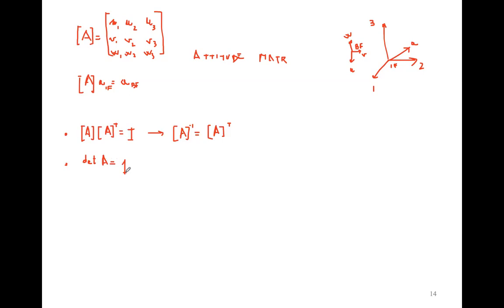I'm not going to reintroduce it, but there is another representation. This is the direction cosine, but you can also represent the same matrix with 3 different rotations. The 3 different rotations are given through the Euler angles. The principle here is that you can use only 3 parameters to determine the orientation of a spacecraft. So another representation here is with the Euler angles.